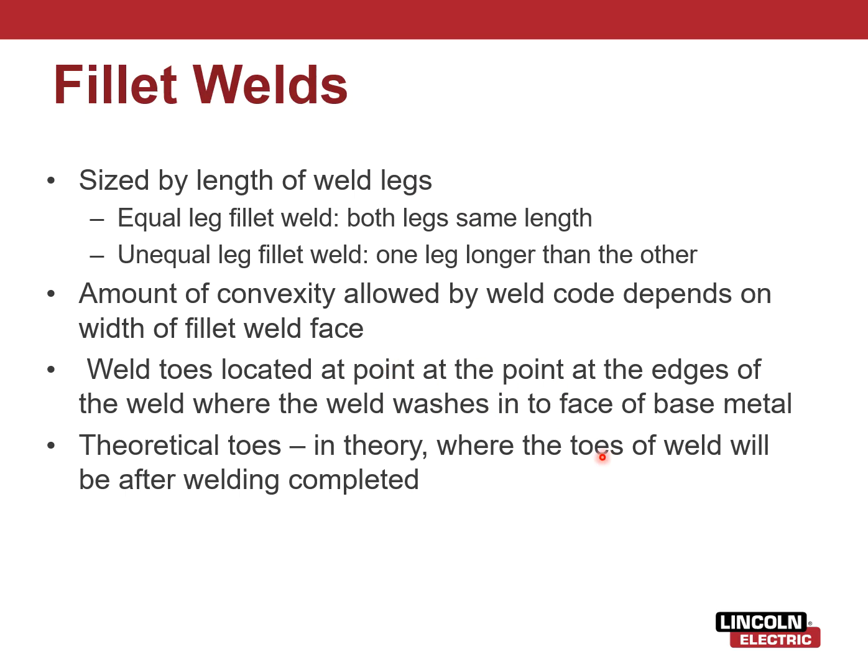Okay, at the edges of the weld, where the weld washes in to the face of the base metal. So that's a bunch of weirdly worded ways of saying the toes of the weld are where the weld material meets the base material. A lot of people call it the edges of the weld. Technical term is the toe of the weld, where the weld material meets the base material. And then the theoretical toes.